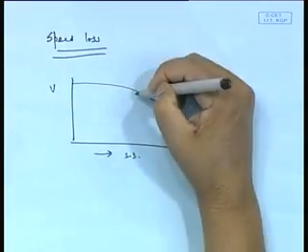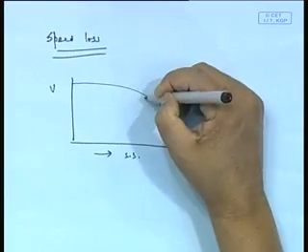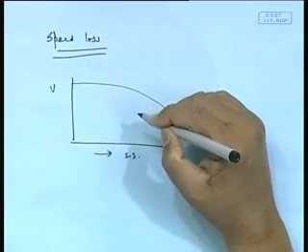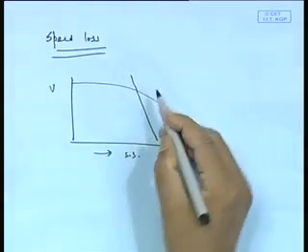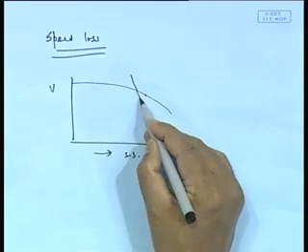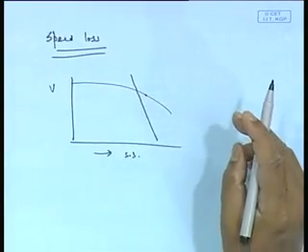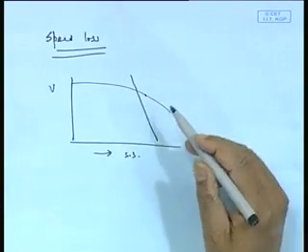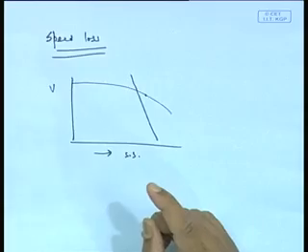But the point, this is just the last part, is that sometimes the captain has to deliberately lower the speed, because it might be having excessive motions. So he might have a cutoff here somewhere. Although the loss is here, what is called voluntary speed loss, he has to deliberately lose the speed, because if you did not, you end up finding that it is slamming excessively.